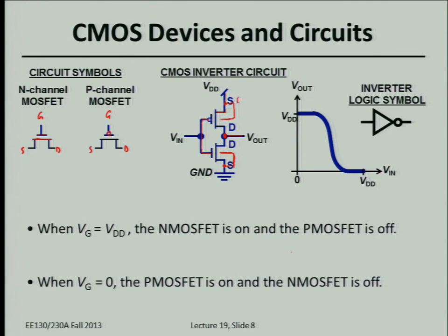Because the source is P-type, and the body is N-type. And you want to make sure that the PN junction between the body and the source and drain never turns on. So you basically want the N-type body to always be biased at the highest possible potential. So the drain can never be biased at a higher potential than the body, to turn on that PN junction. Okay, that's good. All right, so what are the roles of these 2 transistors?